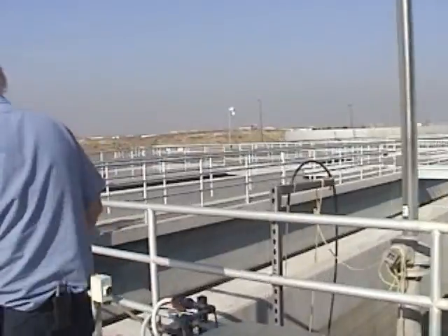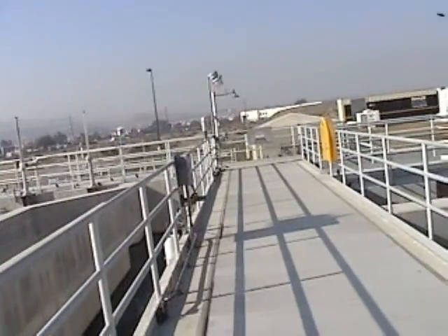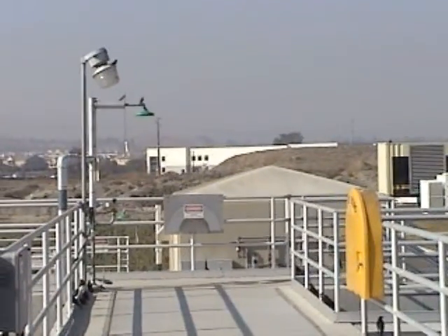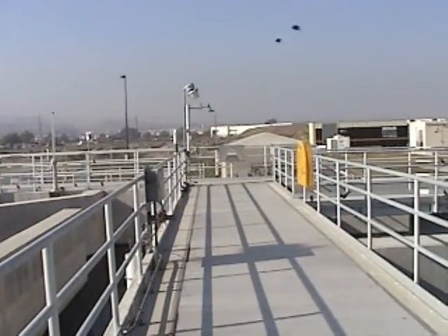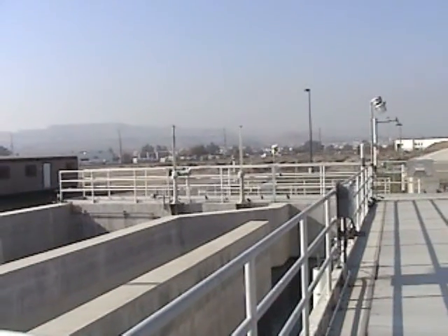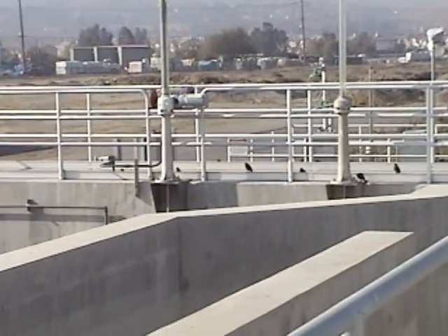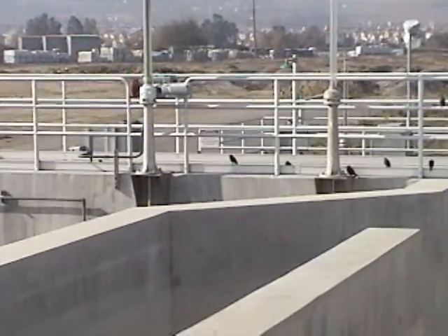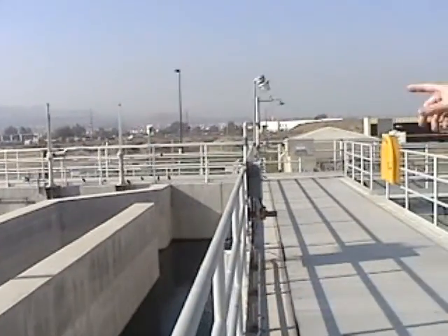The next thing that's going to happen is the flow from the tank is going to come over here. It's going to be picked up by a pump sent to that small building over there, and the Z-chlor, which is measuring for chlorine residual, is basically checking for a chlorine residual. If it sees a chlorine residual after a minute, it's going to shut that gate over there, which is a final effluent diversion gate. So it's really important to respond to an effluent chlorine residual analyzer problem. If it's going low, basically it's going to tell the system we don't have a residual. It's going to ramp the SBS, sodium bisulfite, down and trigger a gate closure.